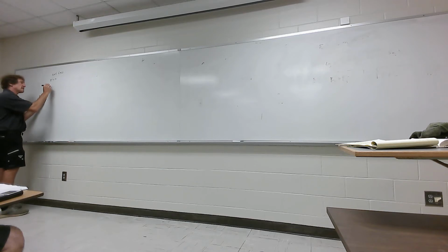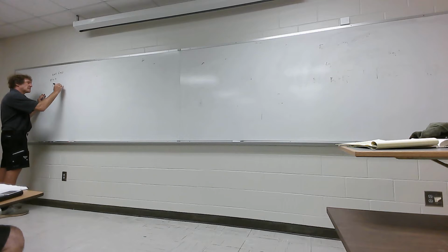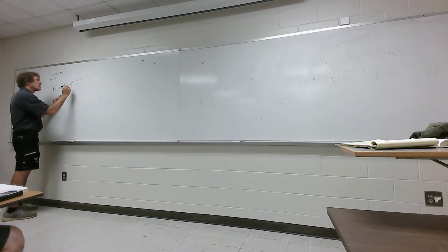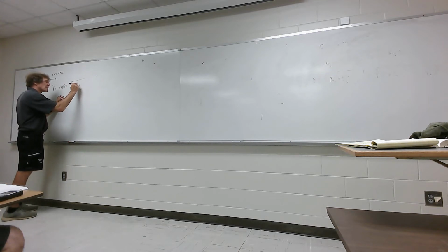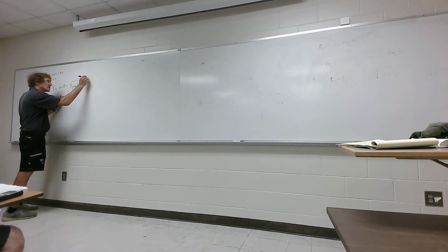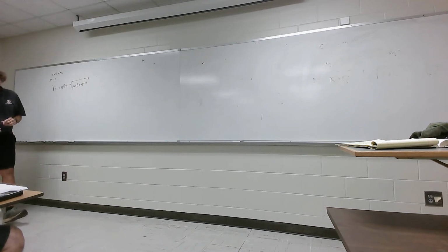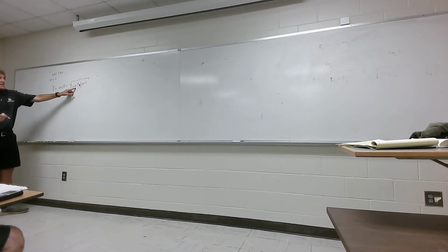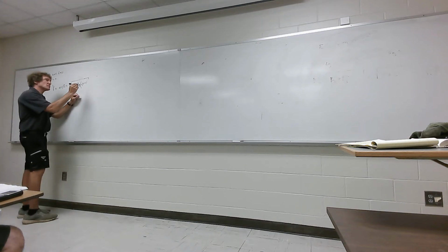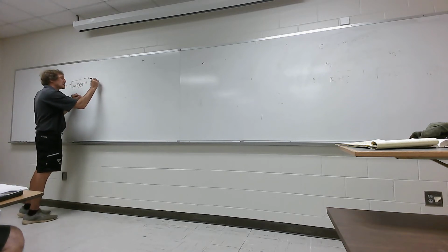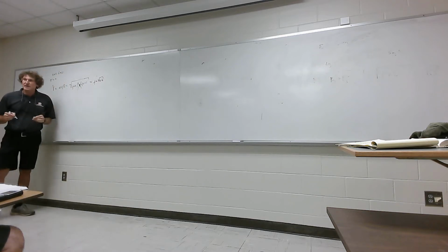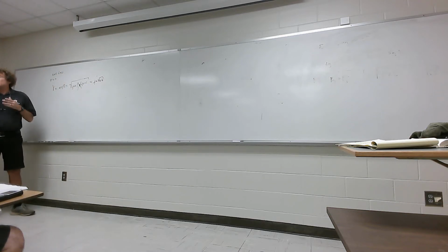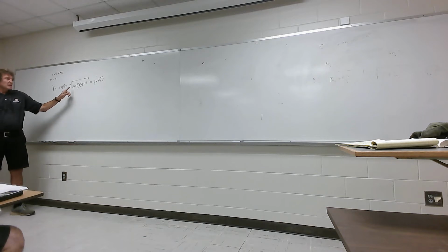That means when you look at gamma, which is alpha plus j beta, that's equal to the square root of j omega mu times (sigma plus j omega epsilon), right? That's fundamental. But if you have sigma zero, then I have j omega mu times j omega epsilon, that's equal to what? Just j omega square root of mu epsilon. Y'all follow me on this, guys? Right, if sigma is zero, then it's j omega times j omega, the square root of that is j omega. And then you have the square root of mu epsilon, right?